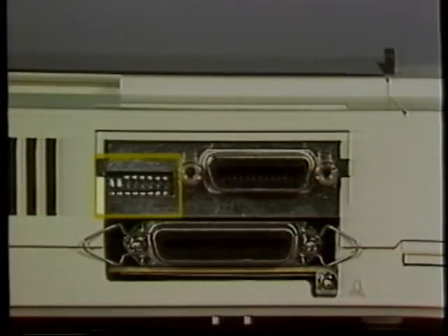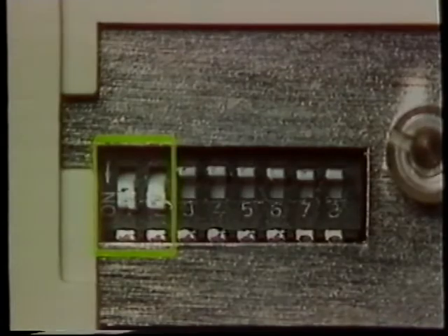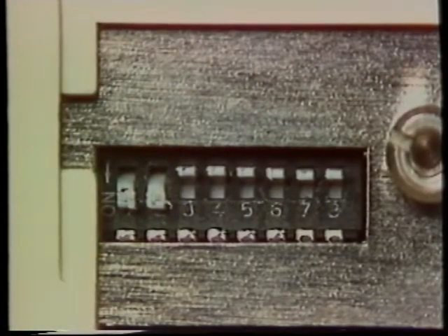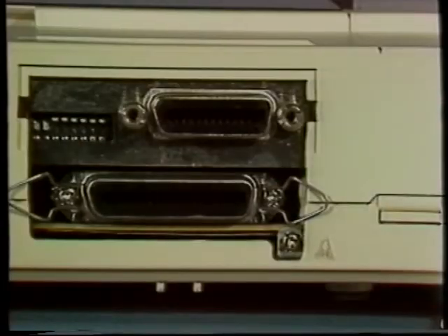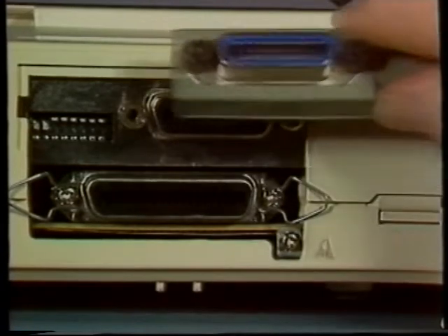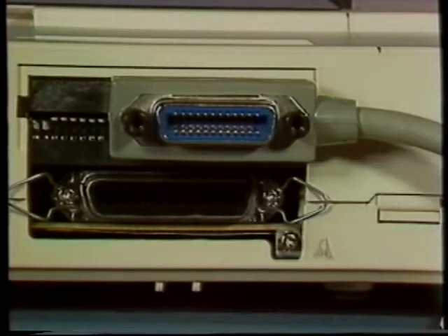The HC100 plotter rear panel mounts the GPIB interface connector and GPIB setup switch. The first 2 switches, numbers 1 and 2, are set in the on or down position, and the remainder of the switches are to be in the up or unselected position. This completes the HC100 GPIB setup. We will use the GPIB port and cable to connect the plotter to the 2230.